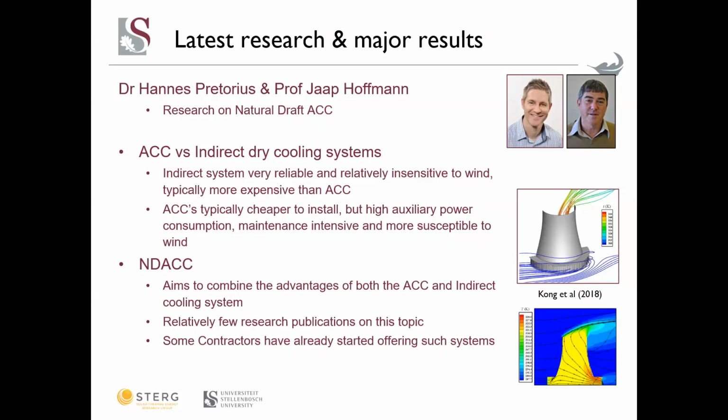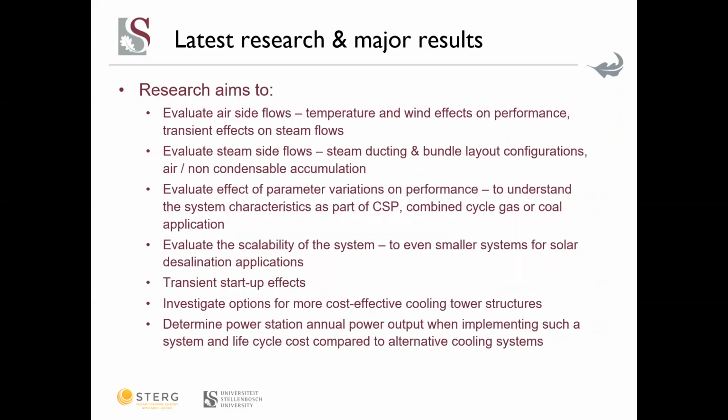As I'm relatively new to the research arena, we want to research this starting at the fundamentals, really understand the basics, and then move to more advanced topics. For this study, our research aims to evaluate the air side flows, looking at the effects of temperature and wind on performance, also later looking at the transient effects of these ambient conditions on steam flows, evaluating the steam side flows, the steam ducting, the bundle layout configurations, and the air and non-condensable accumulation.